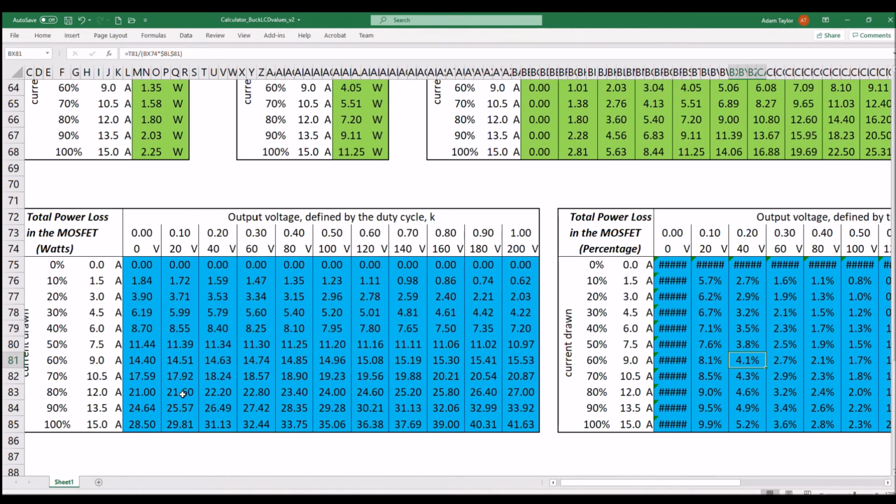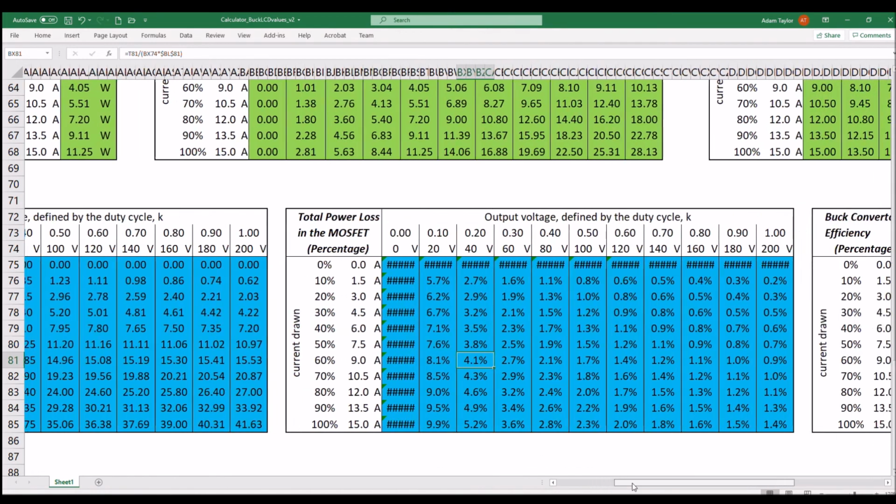And even though we might be pulling very little power out of it because it's only starting up, we're dissipating quite a lot. And then as the machine runs up to full speed, the percentage losses increase slightly, but the total power being delivered is significantly larger. And we see that here.